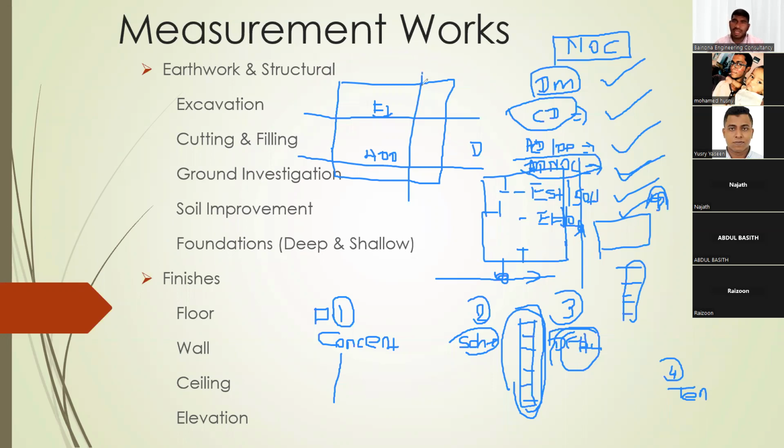That is what they will tell in the no objection certificate: there are no services available in this plot, you can go ahead with the work. Otherwise, they will tell you there is a cable here, a pipe here, a power cable here. First, you have to relocate them, and only then can you start the work. In our current project, we had lots of issues. First, we did this relocation, and it took 6 months just for the relocation.